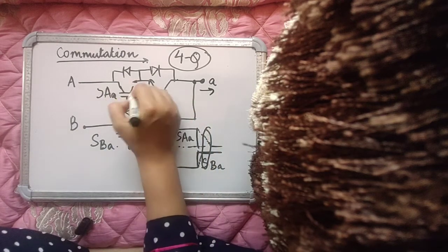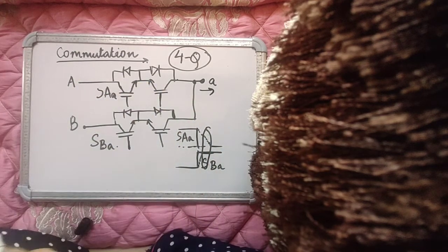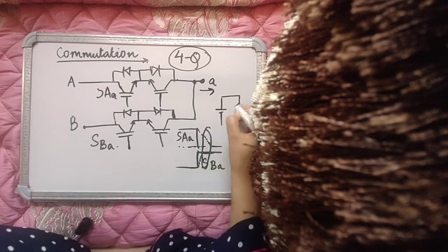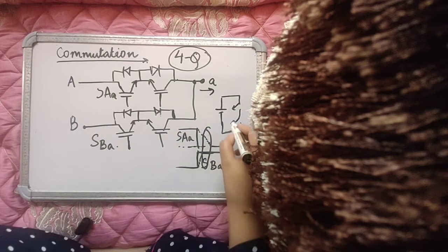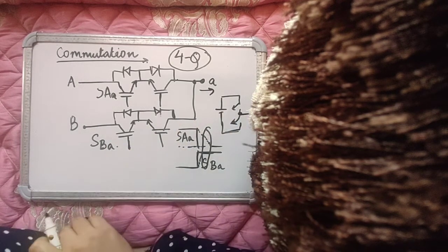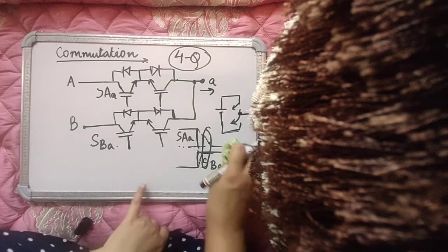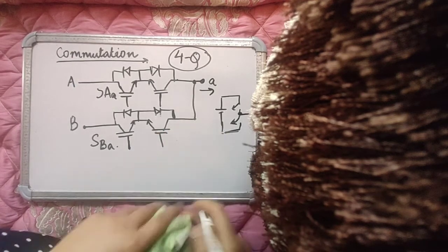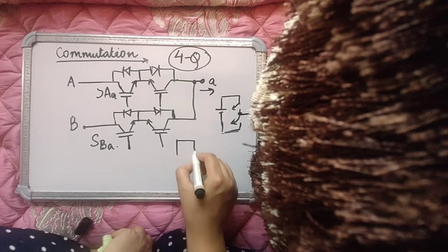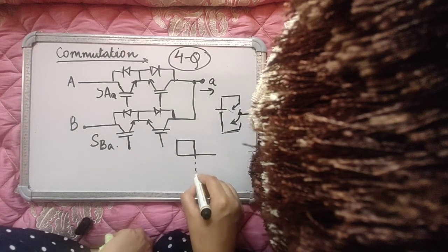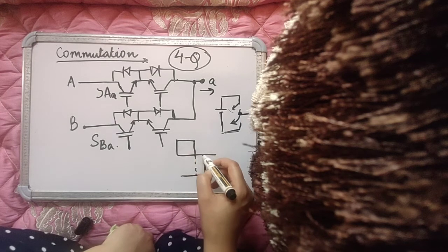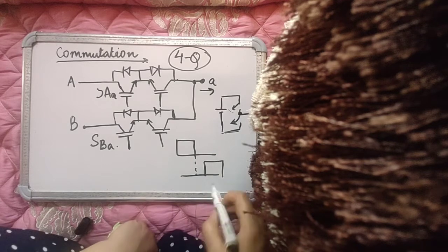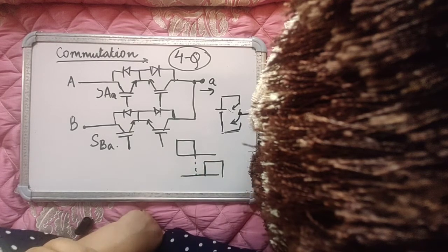In voltage source inverters also this problem is encountered: you have a DC bus, and if two complementary switches turn on simultaneously, your DC bus gets shorted. In that case, what we generally do is that we give a small dead band, right? And I've already discussed it. We give a small dead band, so that one switch is turned on, and then after some time the other switch is turned on, so that we can ensure that this switch has turned off safely, and then we turn on the other switch, right? So you avoid any short circuit condition.